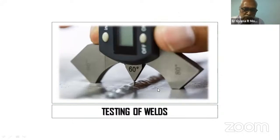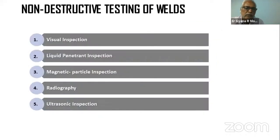So how do we test the weld? Once the welding has been done, we need to see that the weld dimension is proper. Suppose you have a 10 mm fillet or an 8 mm fillet, it should not be undersized. If it is undersized, then it will not have its proper mechanical properties. And if it is oversized, we have consumed a lot of consumables, and that is also not desirable. That has taken in a lot of heat input.